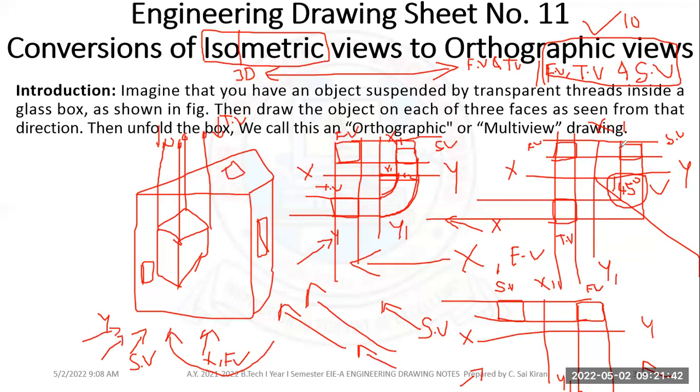Okay. You need to fix your drafter and make the projections. Make sure that your drafter doesn't have any errors. Draw the vertical lines and directly join. This is the best method. Okay. And you have to use an H pencil only. Whenever you are making any projections, use the H pencil. It should be lighter, and the front view, top view, side view should be darker, and you have to use the HB pencil there. Okay.